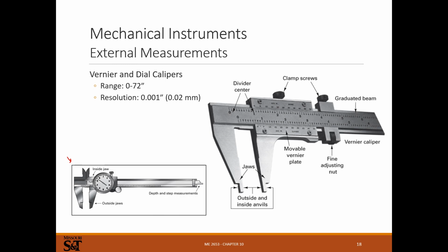If you have the lab for this, great. If not, we'll do a video on measuring different things with these. Essentially you've got a gauge here that'll be tenths of an inch usually, and then this will be in thousandths. This will usually have 100 thousandths going around. So you take the tenths that you read off the gauge, plus the thousandths you count, and you get the dimensions. Again, this needs a video by itself to show you how to use these, so we'll get that for you. But like everything else, buy good calipers.